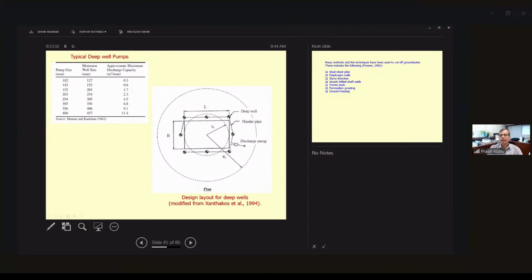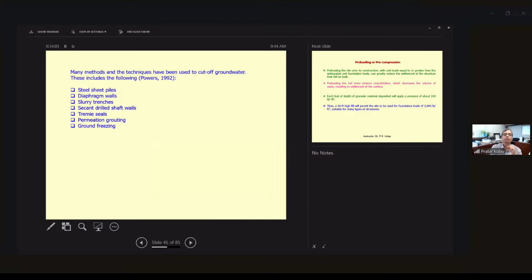So just for example, if you are designing a deep well system and we have a different well point, we need to know how much equivalent area is going to cover. Okay? And then from there you can find out how many wells are required, how much is the total quantity of discharge, and how many wells are required to complete this dewatering system. So I'll be solving some problem, maybe one from here.